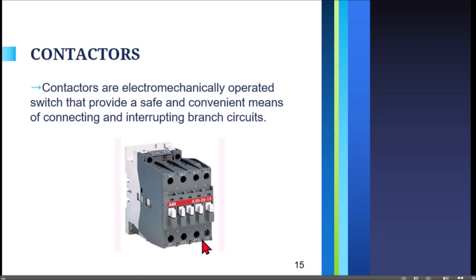Of course, the contactor can be reversed if it is an AC contactor, but if we are going to follow the standard, we must put the proper wires to their proper terminals. Then the last pair of terminals are the auxiliary terminals. As you can see, it is NO, normally open. We will discuss further what is normally open and normally closed later on in this discussion.